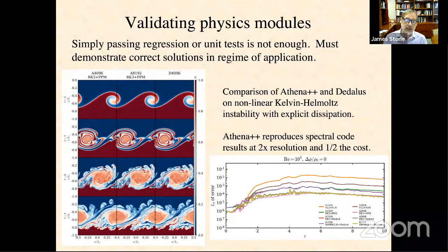And then finally, we need to know that our algorithms are accurate, that they're calibrated, that they're really giving you the right solution, that the approximations we implement in the methods are converging to the correct solutions for the equations of fluid dynamics. You can do that by comparing to analytic solutions, and you can also do it by comparing to other numerical solutions for fixed test problems.